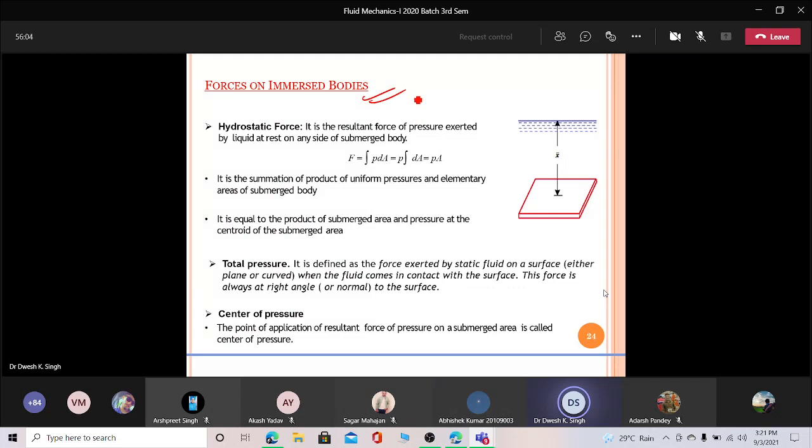Sir, can we use gas in a simple manometer also? No, a manometer is not used for that. It is open-ended. A simple one, no. A differential one you can use. Okay, sir. I have already mentioned this: for gas, a differential manometer is not used because it is closely packed. Yes, sir. For the gas system, we use this Bourdon gauge, the mechanical system. Okay, sir.